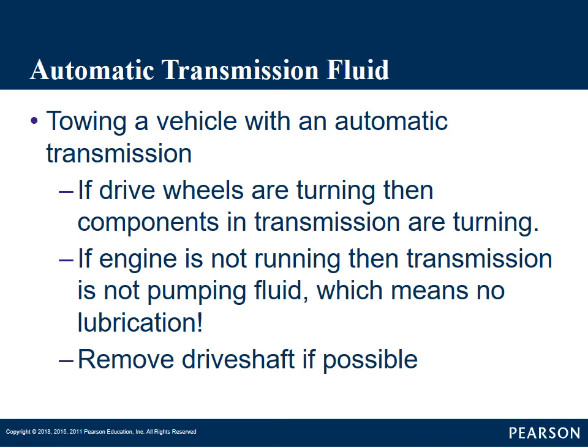If you want to tow it faster or have to tow it faster or over a longer distance, we need to take other precautions. If it's a rear-wheel drive vehicle where you can remove the rear drive shaft, do it. Because if the drive wheels are disconnected from the transmission, even though the drive wheels are turning and the transmission's not, it doesn't need to be lubricated.